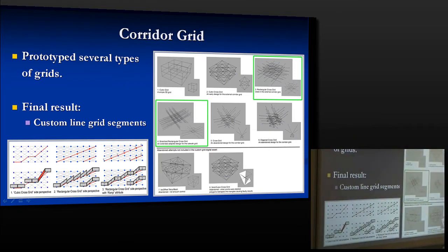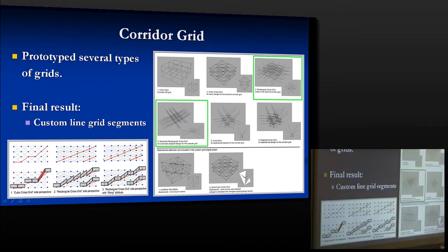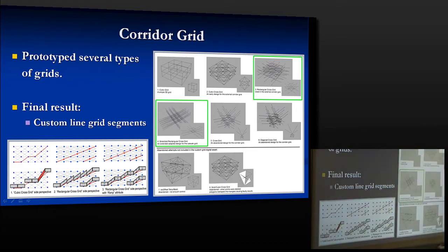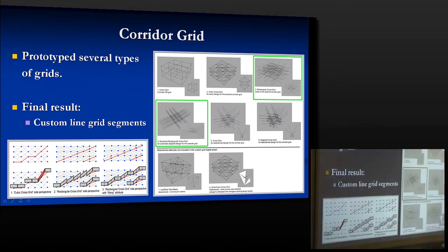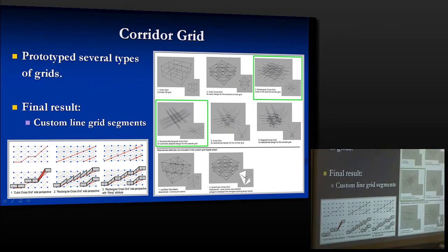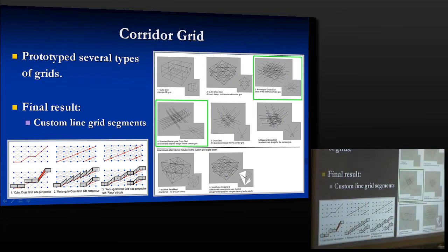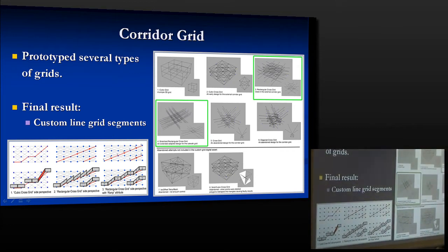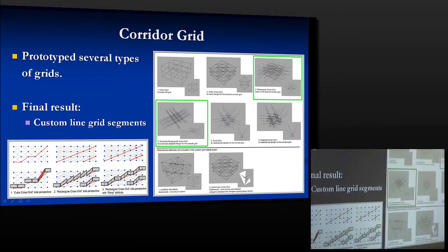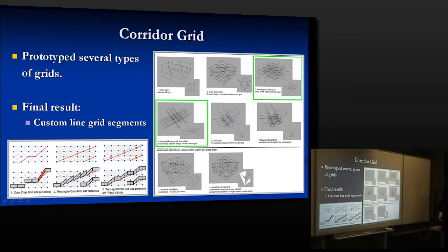So in order to fix that, I stretched out the grid, where the diagonal components cross two horizontal components. So you would actually get something like this, and what you get then is enough space for the ramps. But the system places these components based on the curves that it generates from the grid. So if you have a very long diagonal line, it would create this kind of staggered, seesaw or saw pattern. And in order to fix that, I only placed ramps in the middle of a diagonal segment, but left the ends of a diagonal segment to place flat components. So you get this stepped staircase. Works rather well, for example, for spiral staircases where there's a landing at the corners.